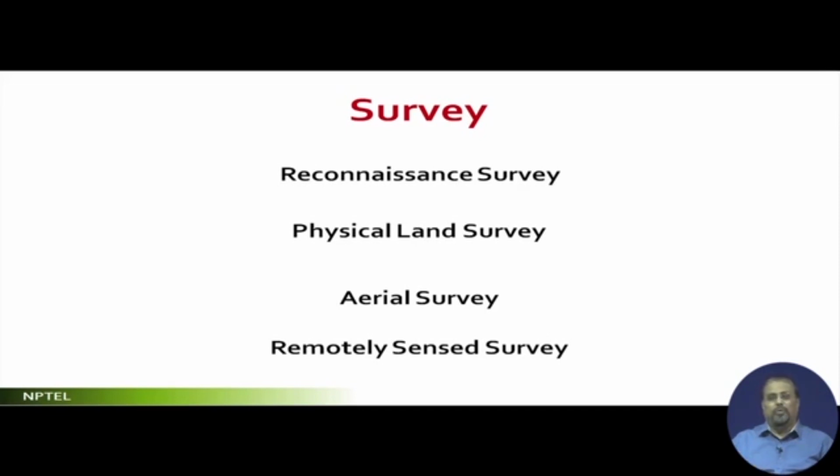How do you go for this? Reconnaissance is when you go yourself to the site. You means you or your trusted representative who is going to bring back the visual pictorial representation in the best possible manner so that you can comprehend it sitting here. Personally, I can tell you what I do. I never rely on anybody else if I am the designer. I don't rely on anybody else's reconnaissance survey. I will go myself to the site and look around the entire site as far as practicable.